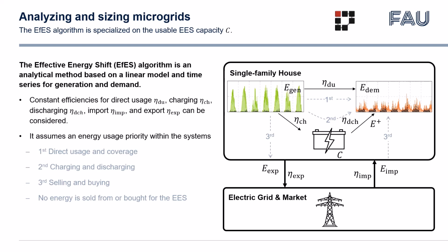One big additional condition here is that no energy is sold or bought for the EES, for the energy storage system. So you don't charge your battery with electricity that you imported, and you don't sell energy that you stored inside your battery system.